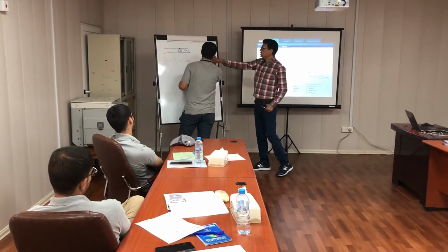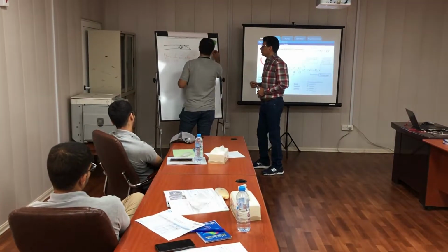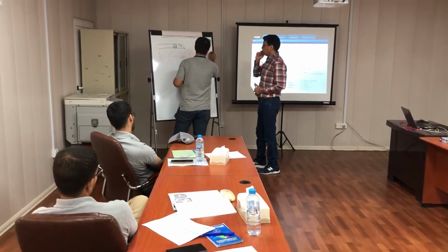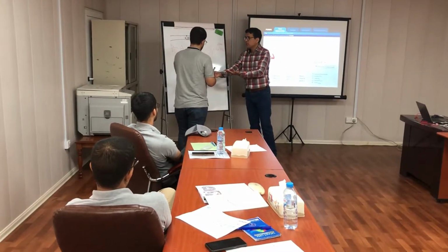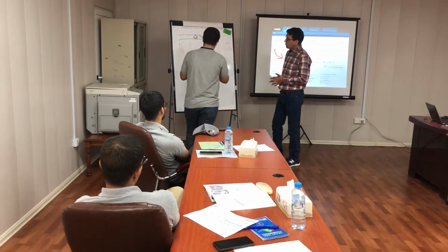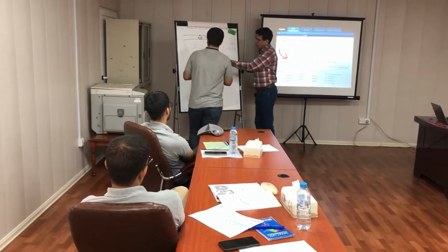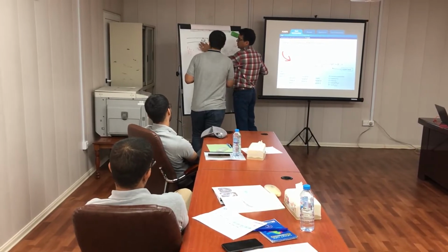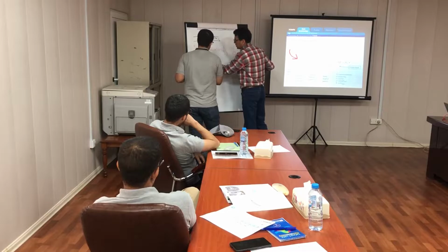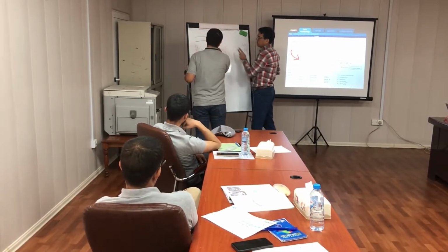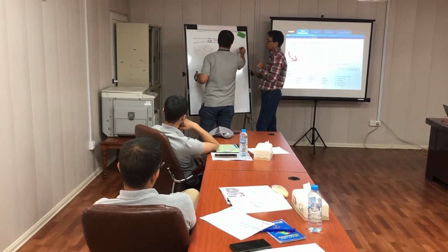Also we don't have a pump here, but we have to write down the formula completely. Okay, which parameter is 0? Which parameter do you know we do not have in this system? We have a pressure differential here. Okay, we have to keep the pressure, the velocity, and the elevation the same as this one.